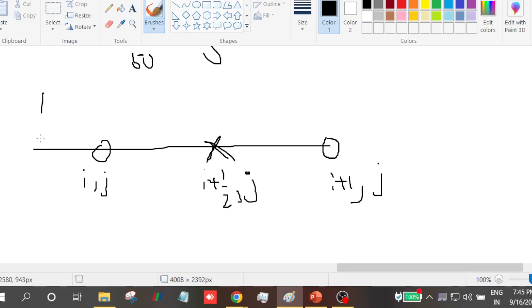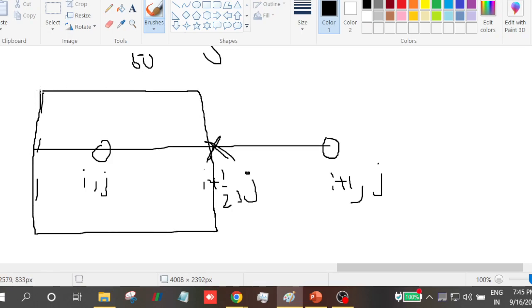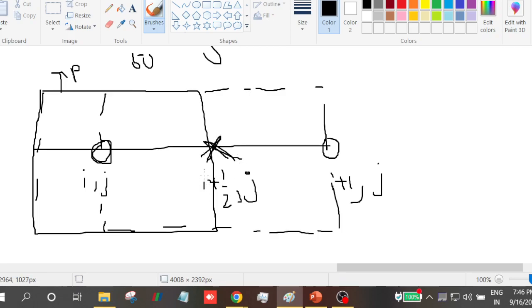So this is the actual control volume, which I'll draw with a solid line, but here it is only for pressure. This solid line is for pressure. The control volume which we consider for the x velocity is these dotted lines. This dotted line indicates the control volume for the x velocity, centered around this point i plus half comma j.